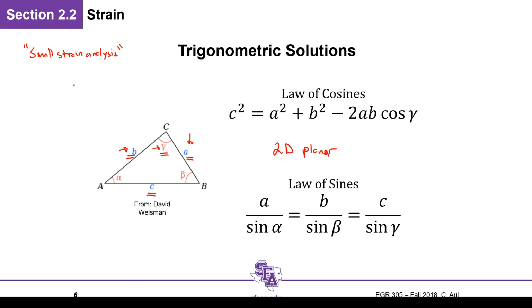Maybe I should rewrite this. The textbook specifically says that if we are working with very small values of strain, right, if strain or shear strain are much less than 1, we can use this idea of small strain analysis,